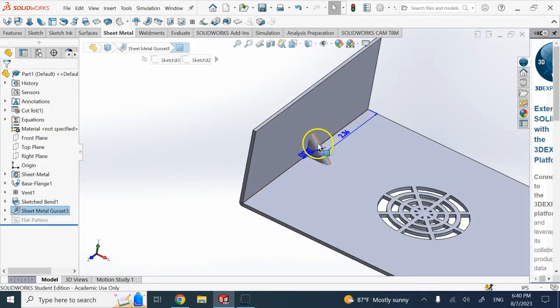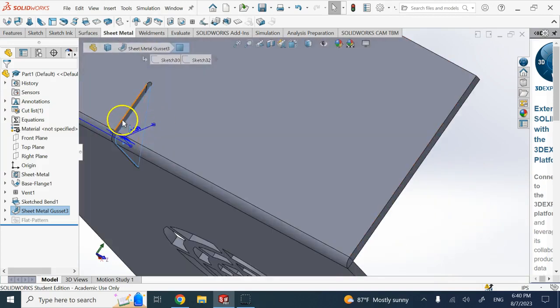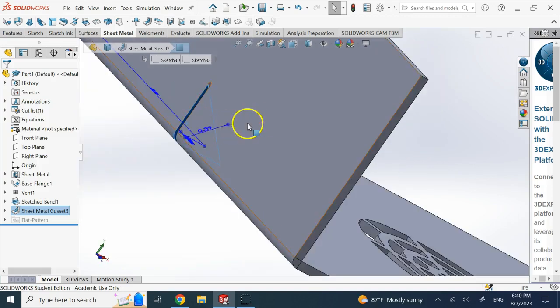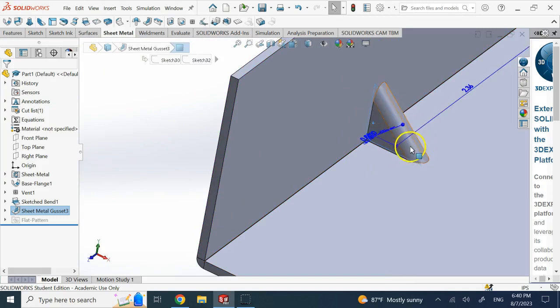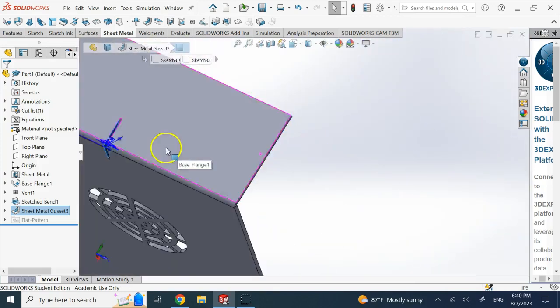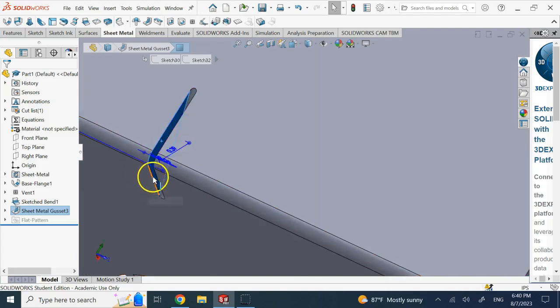So again, this is not an extra piece. This gusset came from this sheet metal by putting your tool here and then pressing against that tool in this direction, and then creating that rib or that wedge. So here there is this gap as a result of pushing the material outward.